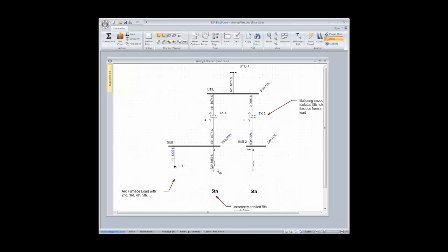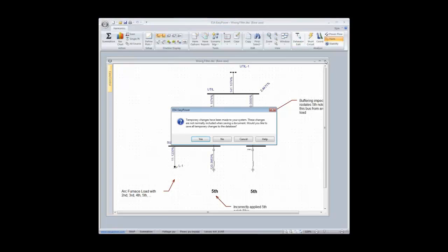Now, the tuning point. Obviously, in this case, we can very quickly discern if we have the right spectral content, that we made a mistake by having this high distortion level. Now, one of the key things that we're going to be using in all harmonic analysis is the driving point impedance scan. So let me close off this case,